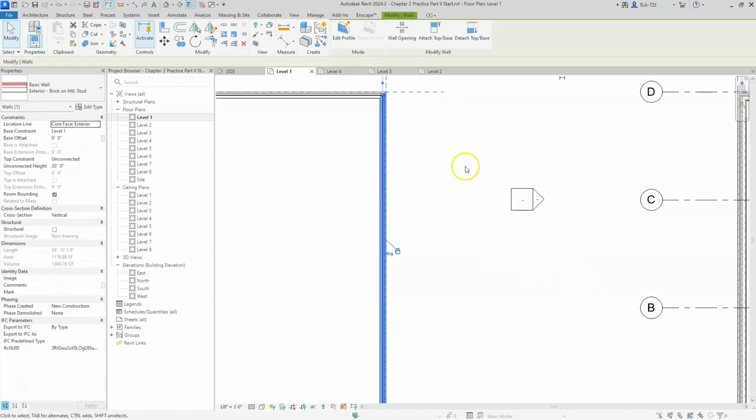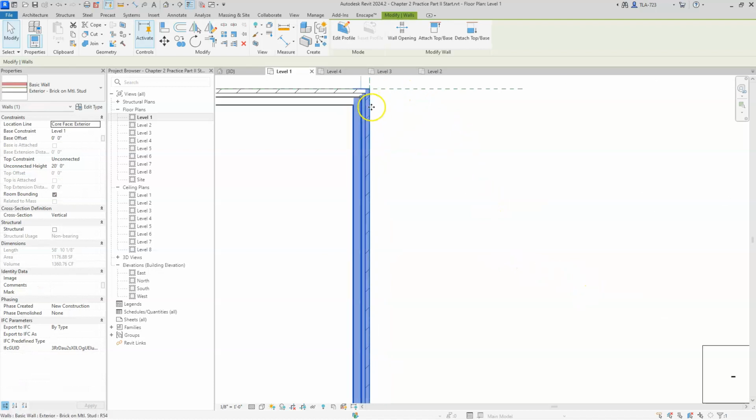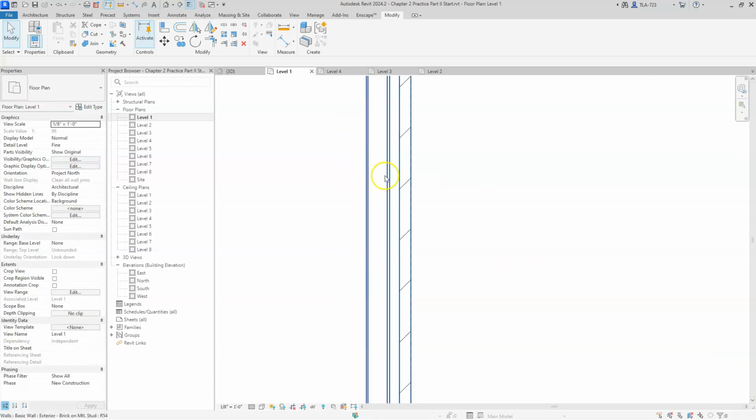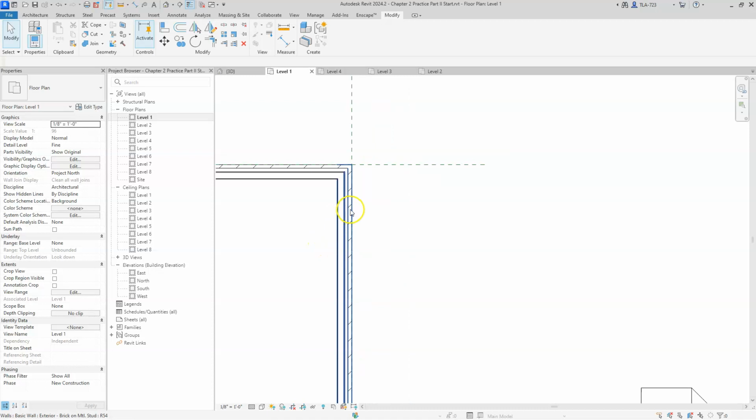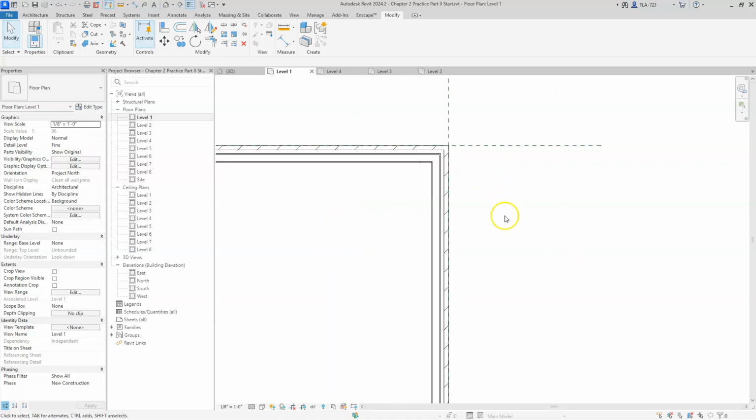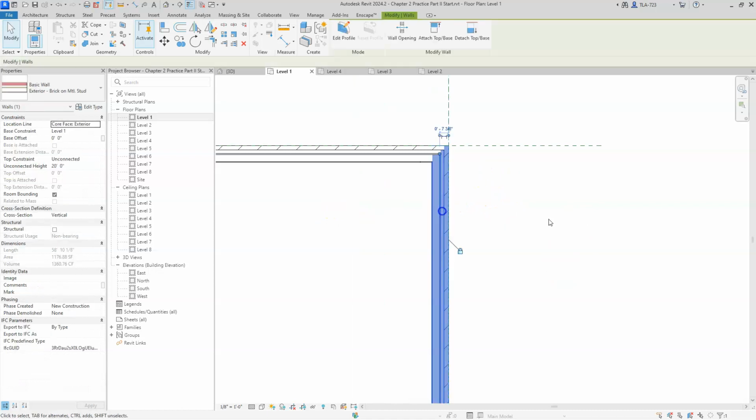We're going to look at the structure of this wall. What we've been looking at is we have a wall, and then we have an outer and an inner piece, and there's all these various layers within there. How is that created? So I just want to give a quick introduction of where that's at. So if we select one of the walls, the properties of that wall gets displayed in the properties palette, and then we click on edit type.